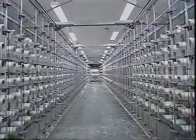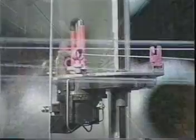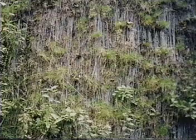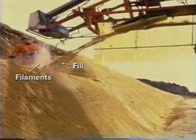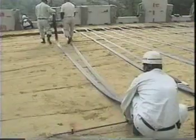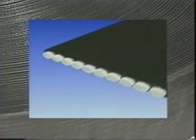The basic element in high-strength polyester soil reinforcement is a fine, continuously extruded filament, typically 30 microns in diameter. In this form, small quantities of these filaments are used for construction of randomly reinforced fill, where filaments and fill are applied together. However, most polyester reinforcement goes through further stages of production. These reinforcing strips we saw earlier are made of polyester filaments sheathed in polyethylene.